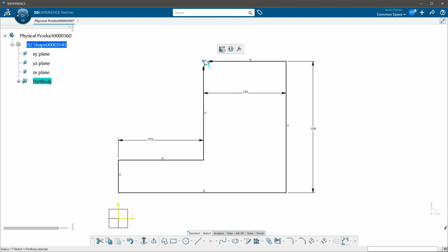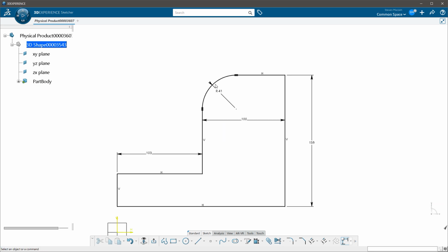So if I want to change this, I can grab that. You'll note, grab the arrowhead, and it manipulates it. So you'll see, again, as soon as I hover over the top of it, you'll see that additional arrowhead appear, indicating that you can grab that, drag it, and drop it. If you don't see that additional non-filled arrowhead there, then you cannot drag and drop the way that I just did. So these dimensions that I'm placing, they are driving the geometry, but they also allow you to manipulate the dimension by simply grabbing that arrowhead, dragging and dropping.